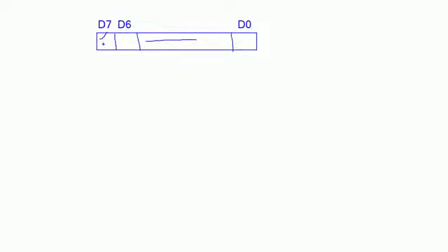Each cell is designed with the help of a flip-flop. If it is a static RAM, which is SRAM, then each cell is designed with the help of a flip-flop, FF. Means in order to hold the 8-bit information, how many flip-flops are there? 8 flip-flops are there. Are we clear? So each bit in the memory location is called a cell, and each cell is designed with the help of flip-flops in the static RAM.